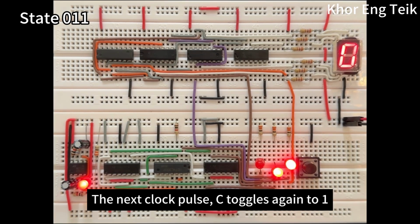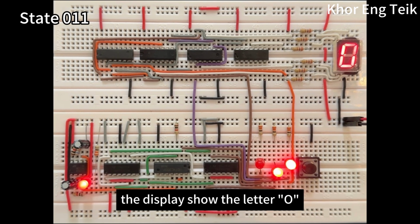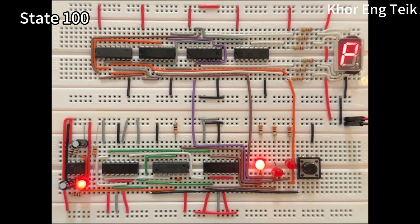On the next clock pulse, C toggles again to 1. Now both B and C LEDs are on, giving us state 0, 1, 1. The display shows the letter O with all segments active except segment G.